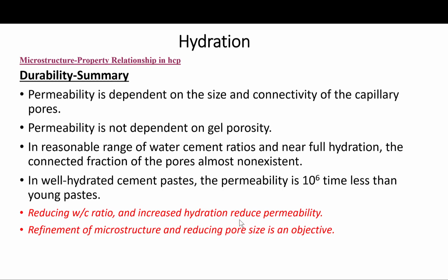These mixtures typically achieve compressive strength levels in the range of 50 to 130 MPa by having low water cement ratio, good curing, and using water reducers and pozzolans. Also, high strength and low permeability concrete can be achieved with low water cement ratio, proper mix proportioning, use of superplasticizers, use of pozzolans, high degree of hydration, and good curing.